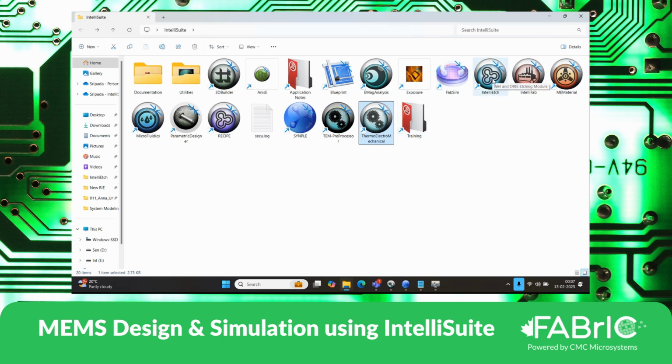So in the case of clean room simulation, we started with how to import, export, or create layout files using the Blueprint module. We integrated the layout with the process recipe in IntelliFab, and then we saw how the lithography and etching activities happen. That is purely from the device-specific recipe, the MEMS device-specific recipe.